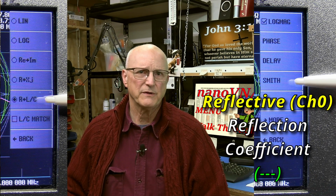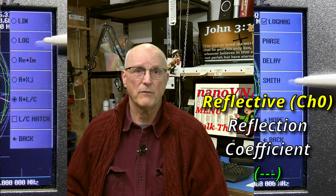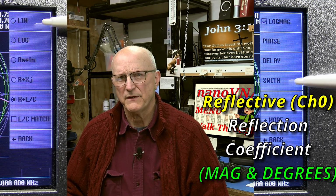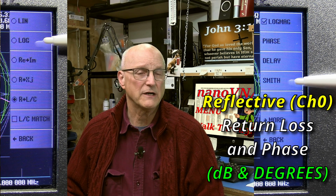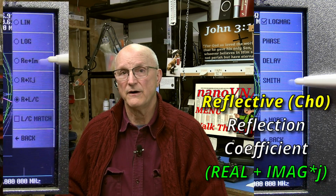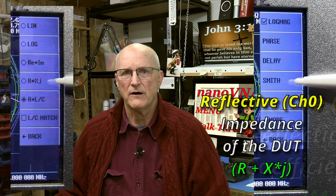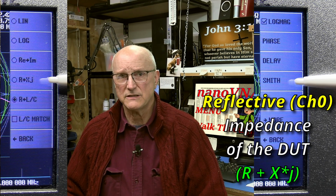You can also display this in terms of the reflection coefficient in both the linear and log marker format. In the linear format, we get the normalized magnitude and phase of the reflection coefficient. In the log format, the magnitude is expressed in terms of the return loss in dB. With the marker Smith values in the format of RE plus IM, we see the reflection coefficient in all of its glory. Then we have the R plus XJ format, which is resistance plus reactance display.